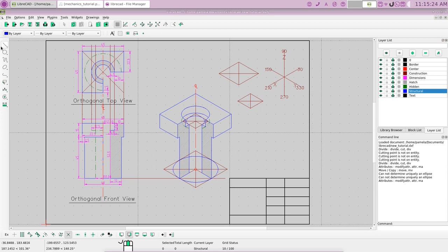So let's go and get a vertical line, and we'll snap on intersection. It needs to rise from here straight up. We're at 40 long. It's a little long, but let's click there. And let's go over here and click here.